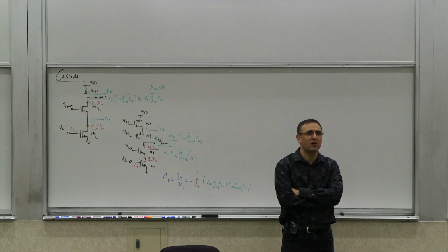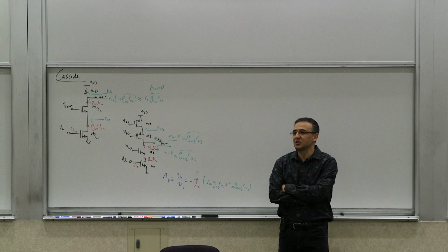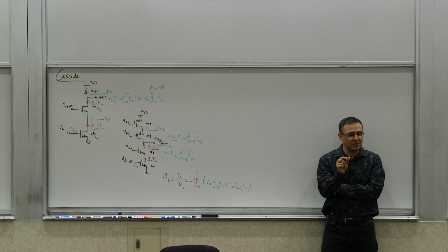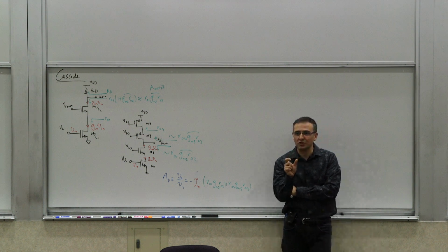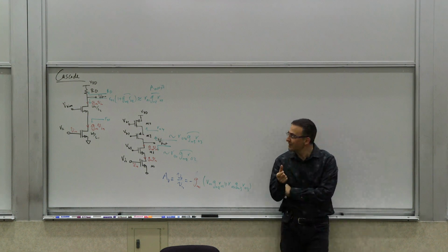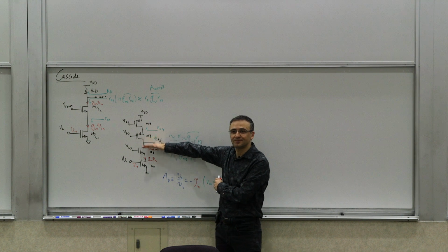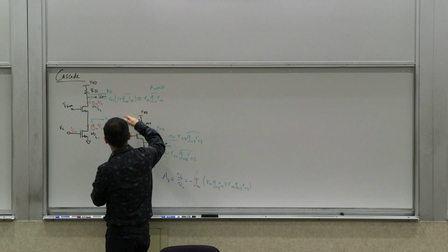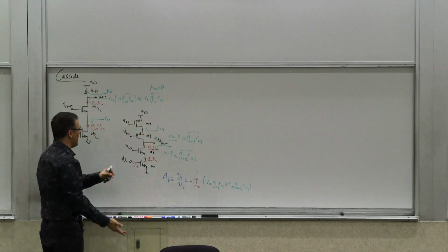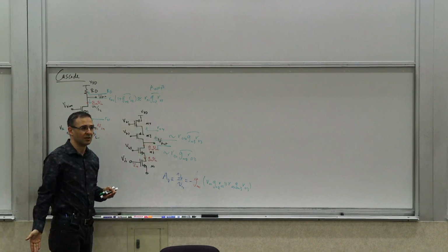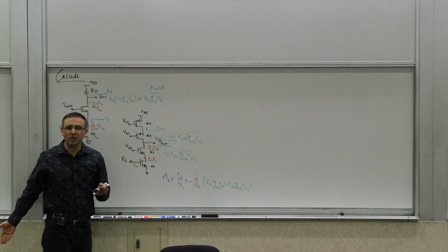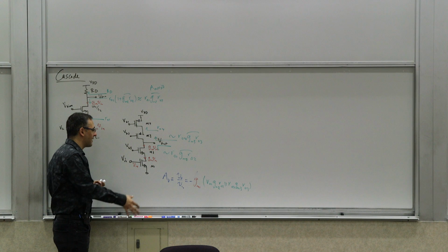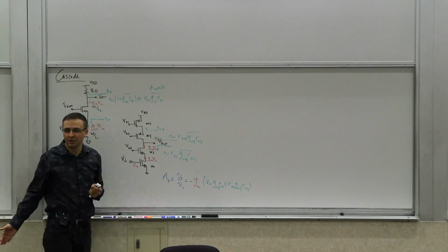We talked about this when we were talking about device physics. And when we make the transistor smaller, what happens to the voltages? We are shrinking the depletion regions, but you have to also shrink the voltages to make sure that you don't exceed the critical voltages. So the supply voltages are shrinking. And as a result, you remember, we said all bets are off as far as this model is concerned if these transistors are not in the pinch-off region. And to be in the pinch-off region, you need to maintain a minimum VDS, which has to be greater than VGS minus VT on every single one of them.